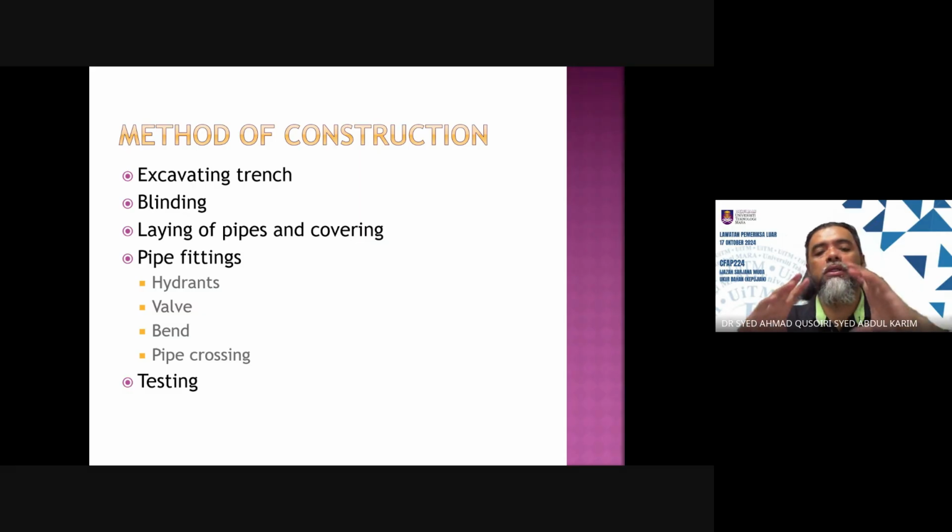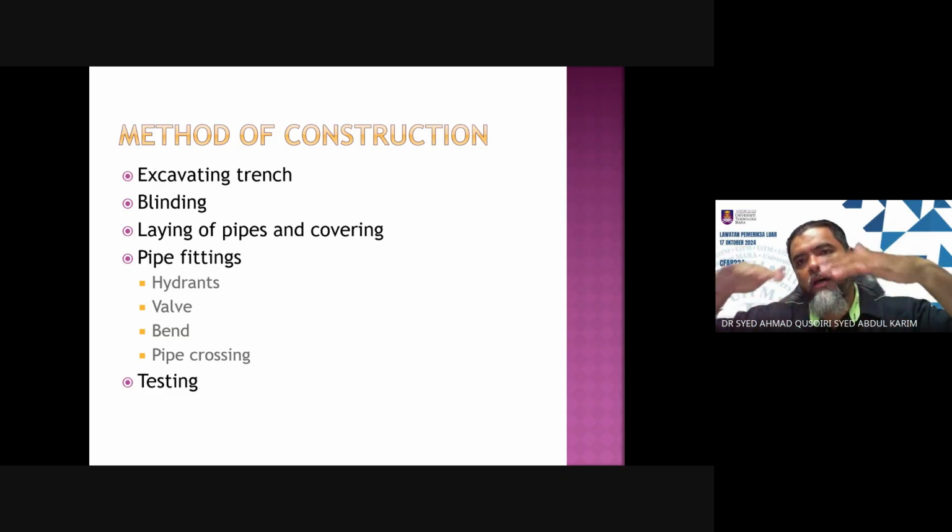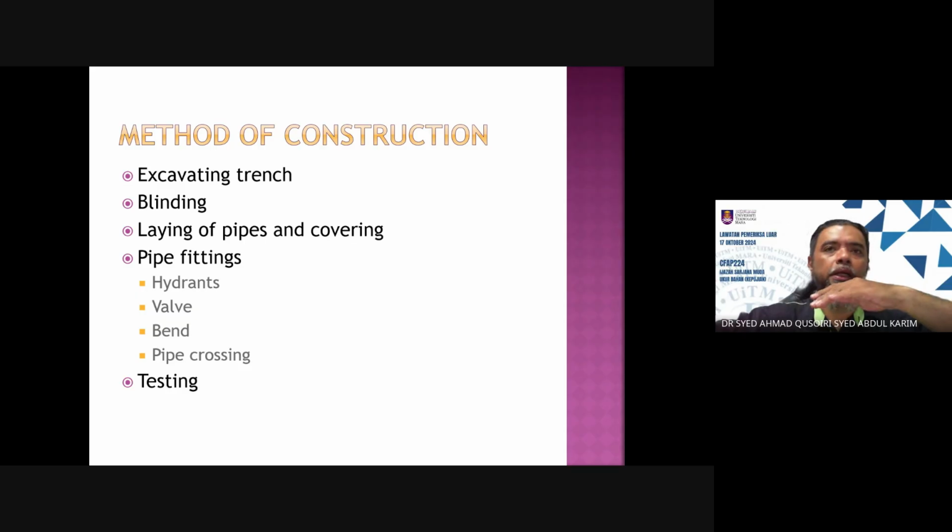The pipe is put into position, and then we have covering with filling material. The material in contact with the pipes is usually sand. After it's filled up, we put in, depending, gravel or soil, okay, to top it up, and lastly, we can also use topsoil.